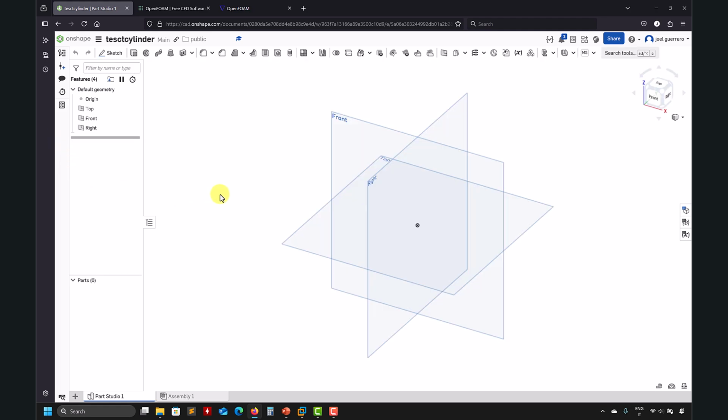And there you go. So this is your graphical user interface. You have your canvas, you can access everything, you have different tools. If you haven't used any CAD tool before, this will get you familiar, because the tricky thing is that to create solid models, you don't start from primitives. You need to start from sketches. So you need to select a reference plane where you want to do the sketch. Let me select the front plane. See that it is selected, it becomes orange. If you want to deselect something, press spacebar.